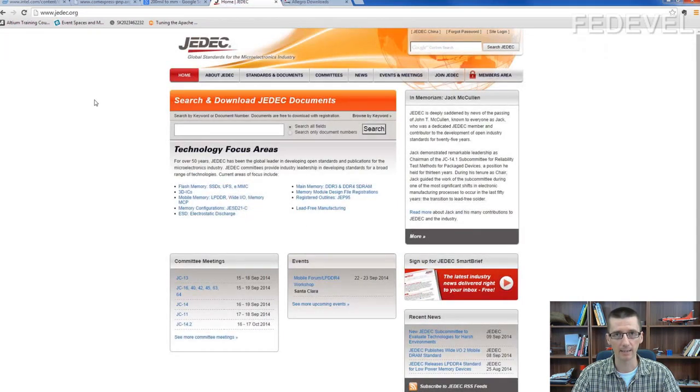I highly recommend you, if you are working with memory interface, go here and download some of the examples. It will help you. I do it exactly the same way. If I'm not sure, I find the specific module here and I have a look how the professionals did the layout.